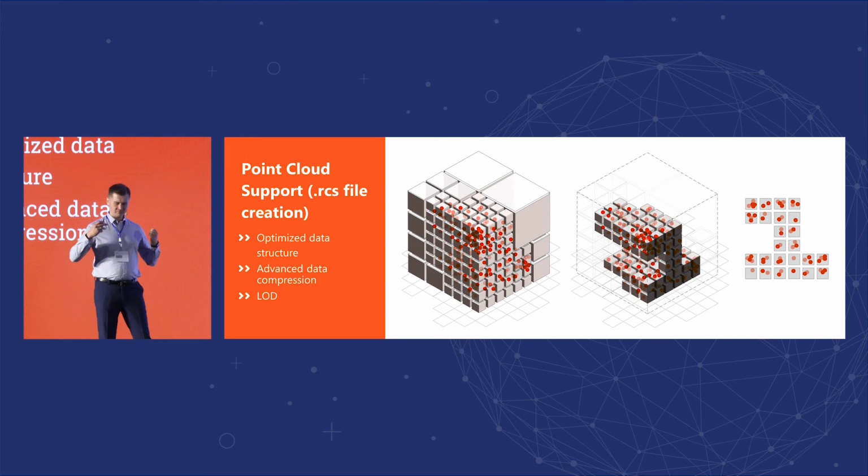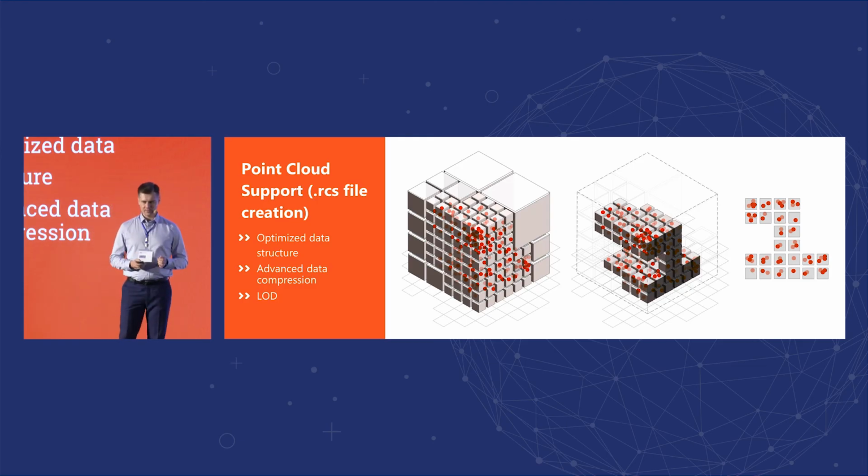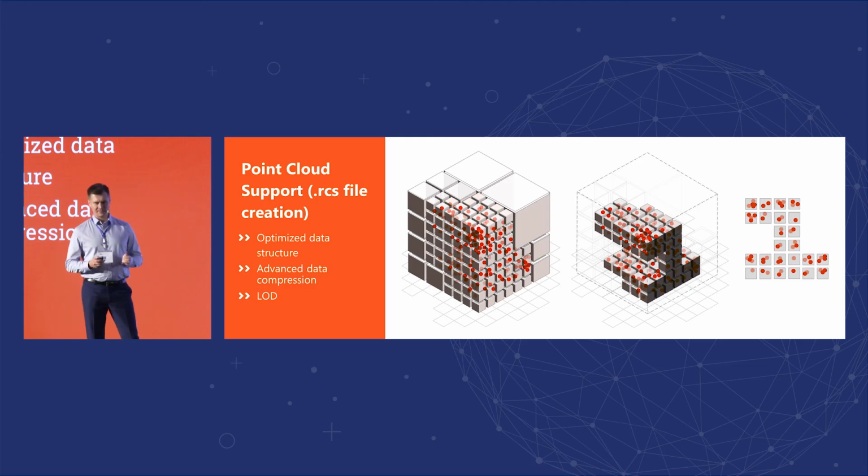But it's necessary to add even more efficiency and to deal with a feature that is called level of details. Level of details is the number of points that should be visualized for a particular voxel depending on a particular zoom level. And it was revealed that it's more efficient to have a set of pre-calculated levels of details and to pick up the proper one depending on our zoom level.